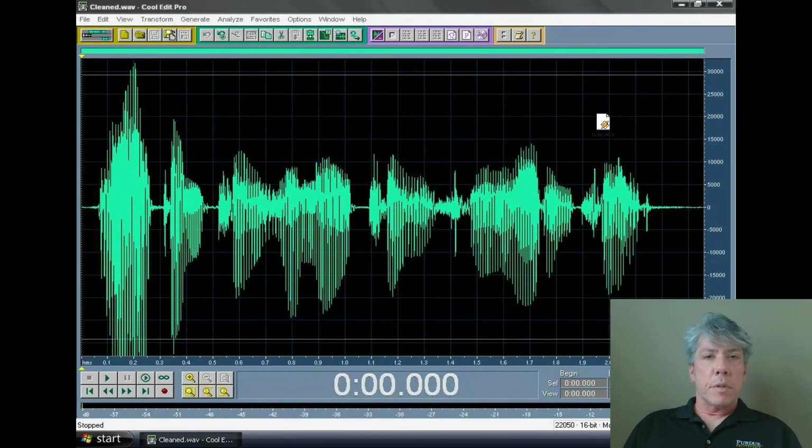Some of the principles of analog signals interfaced to PLCs can be difficult to understand, but you actually do have some, I wouldn't say experience, but use of the concepts that are very important. For example, analog inputs have to be sampled in order to come into the PLC. The PLC is a discrete thing, right?